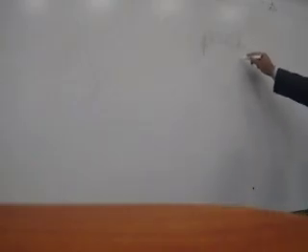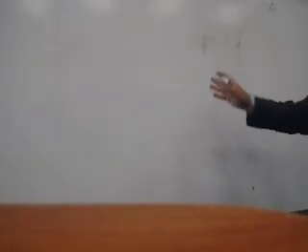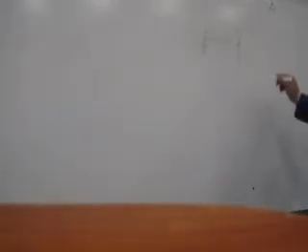It's now there. Like, to make this portion stable on its own, can I just leave it and it will fall? No. So there must be an internal force that keeps it apart. So this internal force acting like this, which is in the same direction of this thing, we call it the shear force.